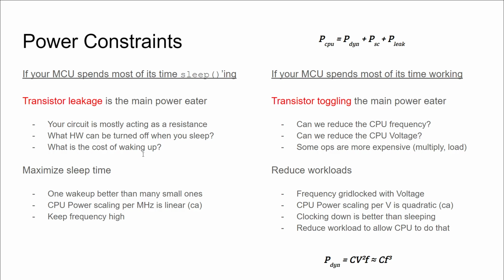Now, by comparison, you got the always-on MCUs. These are MCUs that are constantly doing something, you never turn them off. The traction control controller of a car is a great example. It's responsible for detecting if your car is sliding along the road and applying brakes if you are. And you don't want to turn that off. You want it to check this as frequently as possible, because the more times it checks this per second, the less latency you have before it starts doing something about the situation.